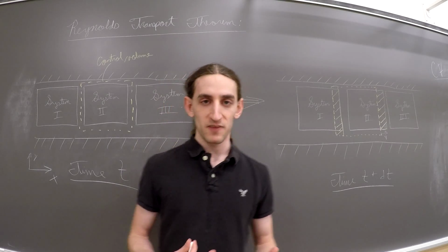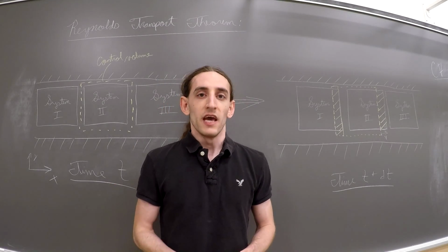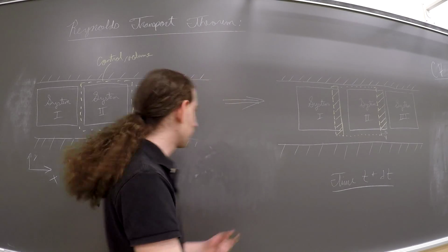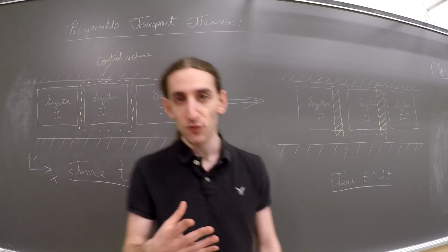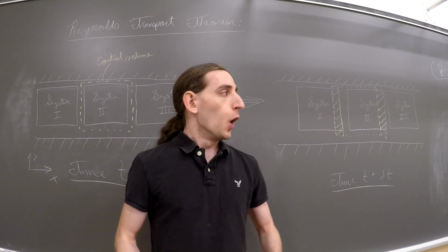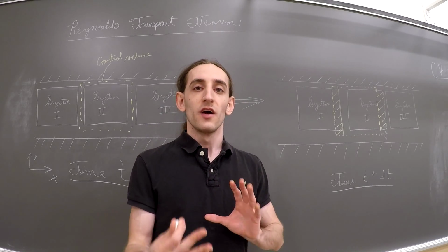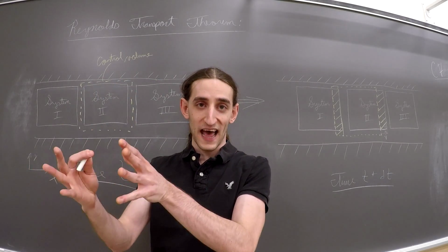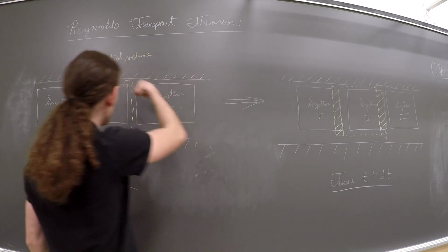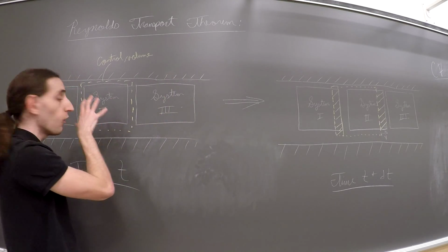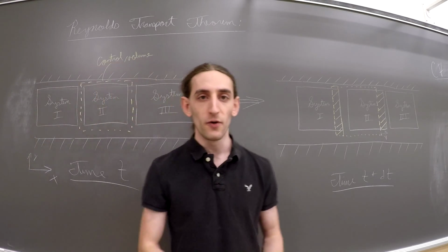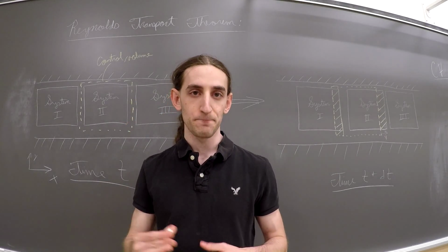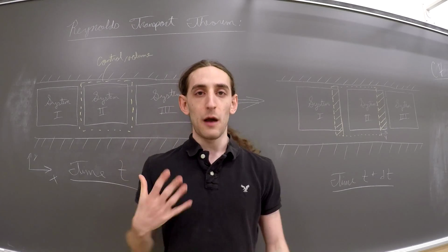If we back up a bit, the main purpose of what we're doing here is to relate the extensive property B of our system to the control volume we're trying to analyze, right? That's done because we want to apply those nice conservation laws that we have in solid mechanics and bring them over to fluid mechanics, such that we can apply them to a given region that we're interested in, basically our control volume. So we're going to figure out how the system property is related to the control volume property, and to do that, we're going to use these diagrams that we talked about previously.